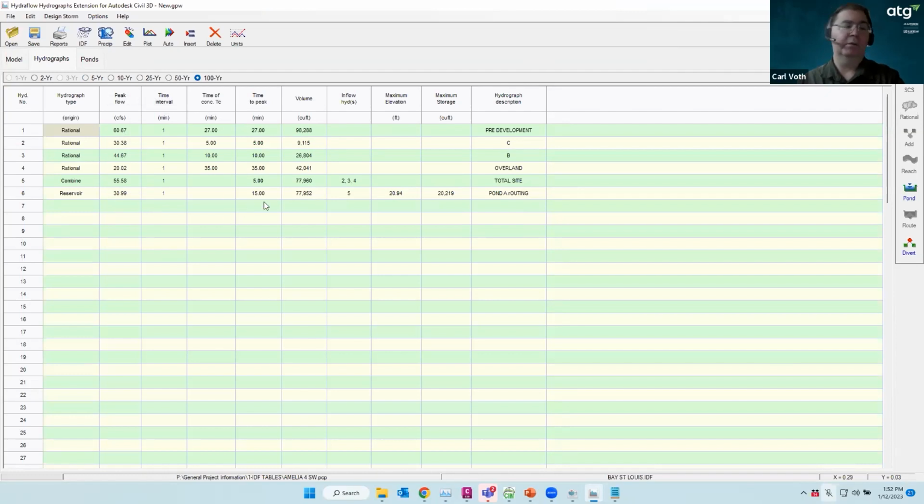Now, if you're in areas where you're running a 1%, if your site is 1% of the total drainage area, then you're going to need to verify this information to make sure that you're not exceeding that. I think that's in Virginia is where I ran into that, in which case you can use StreamStats to get that overall drainage area from there.